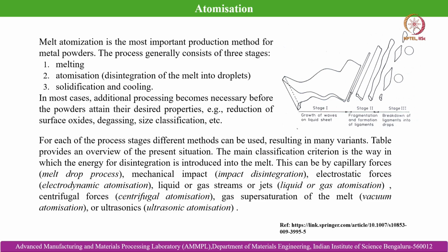So, we will discuss some of the techniques which do not exert that much pressure, however, which are very much beneficial and popular as a PM technique, and also capable of providing parts in net shape. So, not near net shape, that means without any need of any post machining. For example, powder injection molding, we will be discussing that a little later, but before that let us discuss the powder preparation techniques in detail.